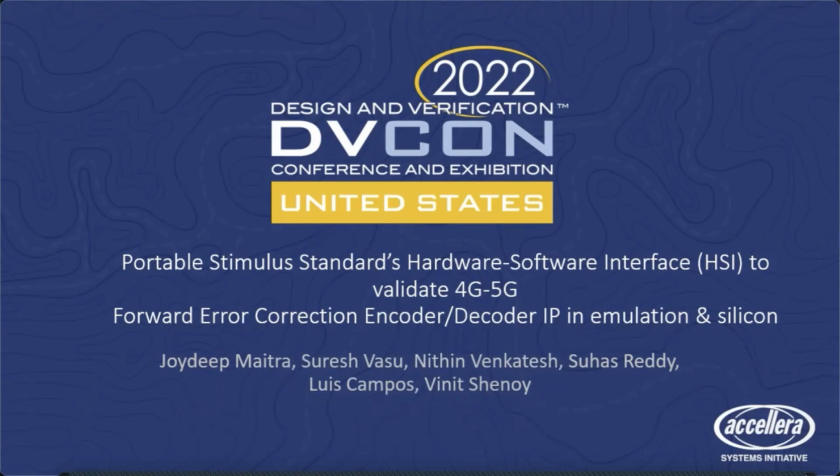So the topic I'll be talking on today is portable stimulus standards, hardware software interface to validate 4G 5G forward error correction encoder decoder IP in emulation and silicon. So what we will focus on is what HSI brings to the table, how we implement HSI in our PSS flow, and finally why HSI makes PSS actually portable. So wherever you stand on the verification spectrum from pre-silicon to post-silicon, from IP level to SoC level, I'm sure this paper will have some useful takeaways for everyone.